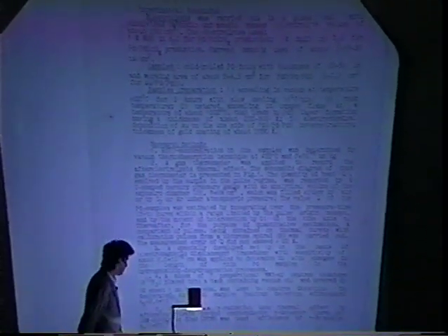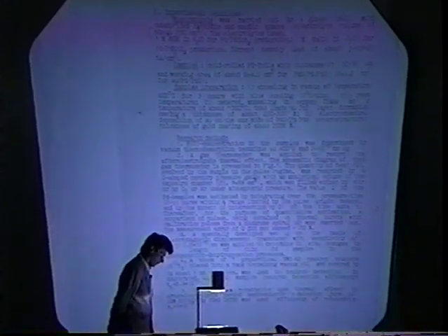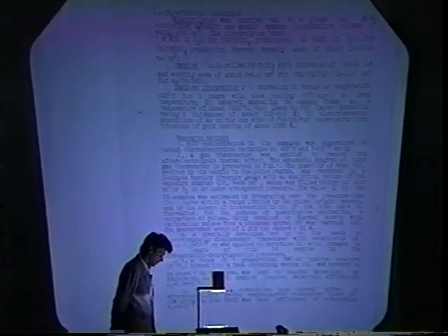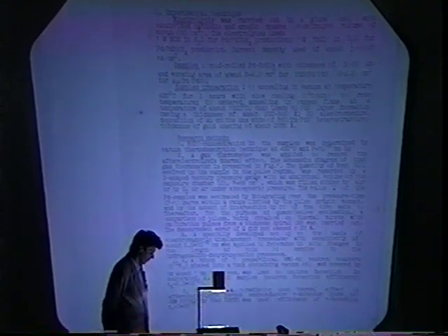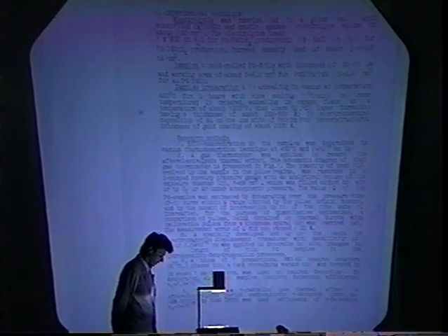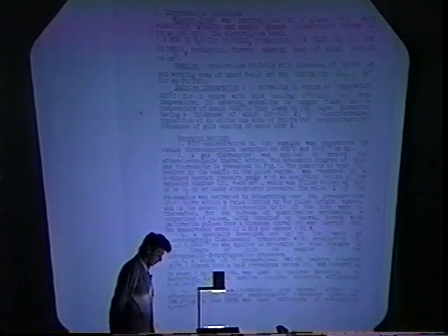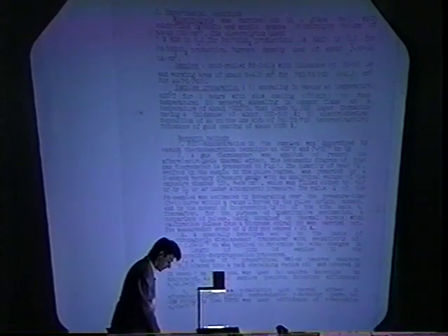The sample preparation was as follows. First, annealing in vacuum at a temperature of 600 degrees Celsius for 3 hours with slow cooling to room temperature. Then annealing in an oxygen flame at a temperature of about 1000 degrees Celsius, which leads to a palladium oxide layer formation having a thickness of about 200-500 angstroms. And then electrochemical deposition of gold on one side of the palladium oxide structure. Thickness of the gold coating is about 2000 angstrom.